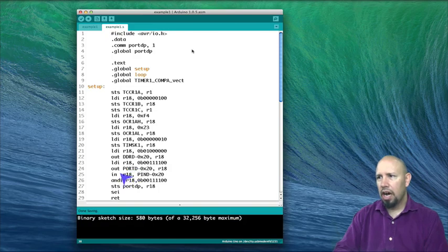And now I'm going to read from pin D. So notice again I have this offset. I'm going to read from pin D, and I'm going to take that value and AND it with these values so that this masks off pins 2 through 5.